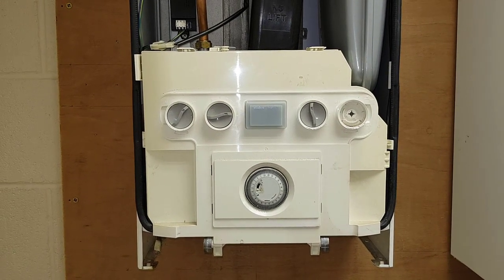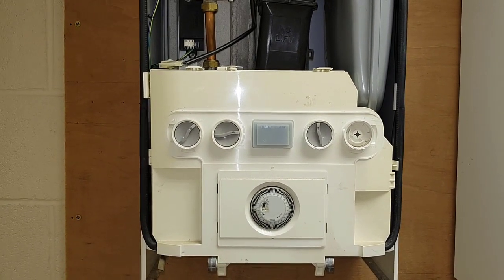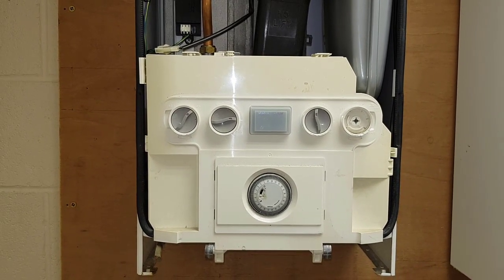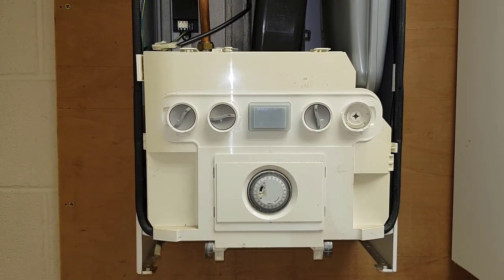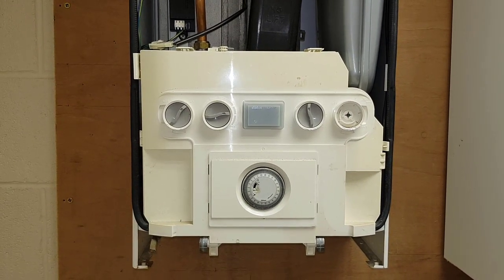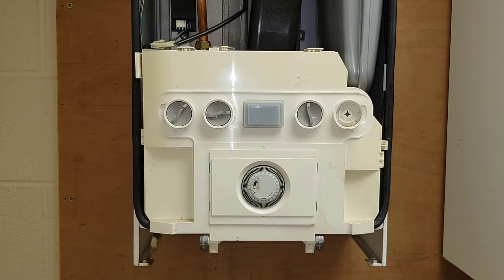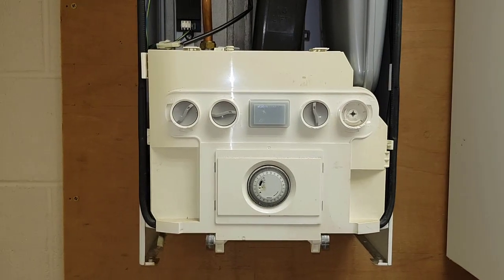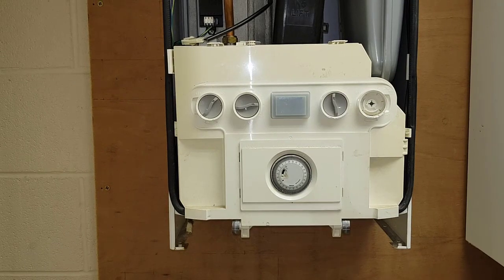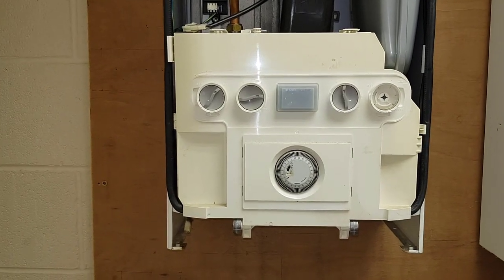Okay, so you've got your quadrant and you've listed what you're going to look at. Let's just go through the list we've got. We'll just do it step by step. We're going to look at the first one. What's the first one on your list for no central heating? Room thermostat. So you've got a room thermostat timer issue.